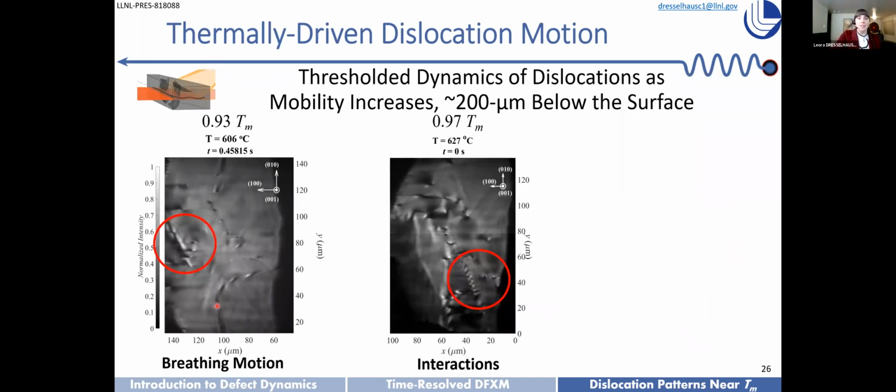However, as I increase the temperature very quickly, I saw this coarsen into single dislocation objects that are indeed discrete, and we can watch how they pack either into grains or into dislocation boundaries. And you'll notice here that these dislocations are moving around in this stop and go, jerky fashion. This is incredibly characteristic from TEM experiments of how dislocations move around through a field of obstacles.